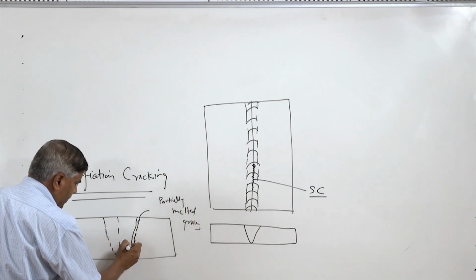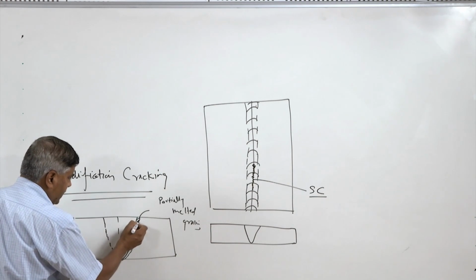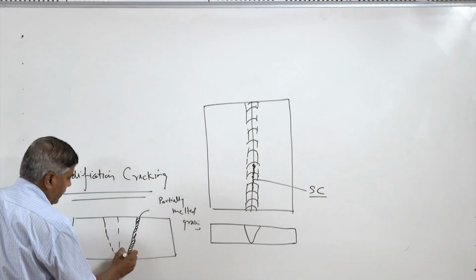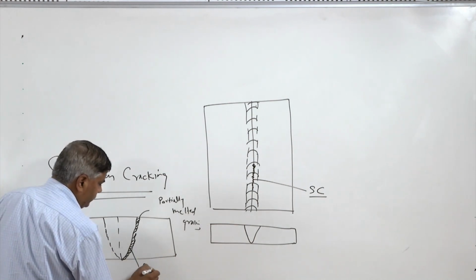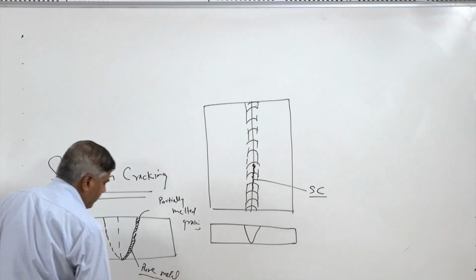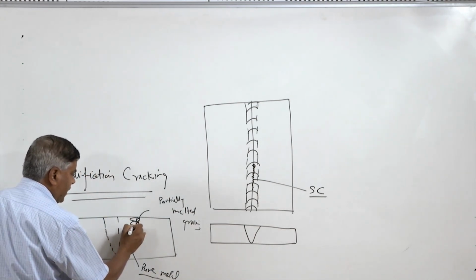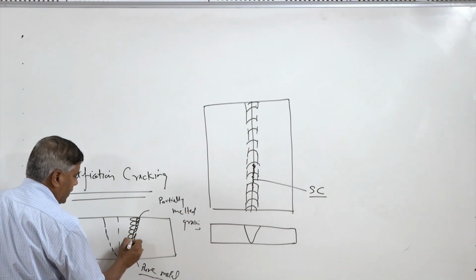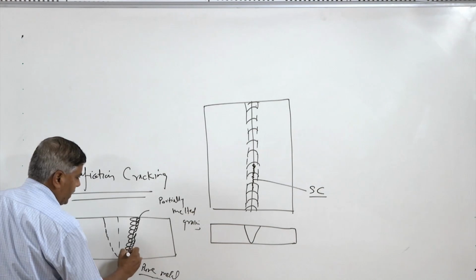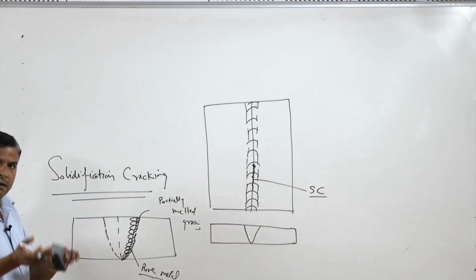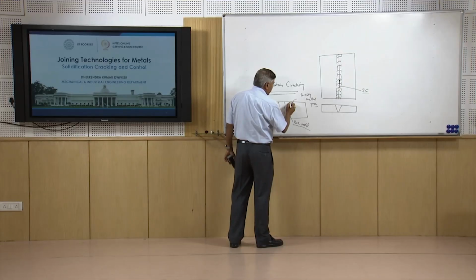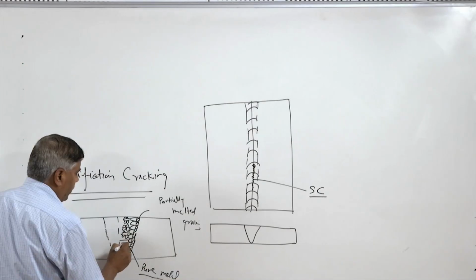In epitaxial solidification, it starts with planar solidification, which is almost pure metal most of the time, and then it will have the cellular structure like this. So, solidification proceeds by consuming the liquid metal, and the impurities or alloying elements are rejected into the weld metal. After the cellular structure we have the dendrites like this. The dendrites also grow by consuming the liquid metal and rejecting the alloying elements and impurities into the weld metal. So, this is how things will be growing from both sides.